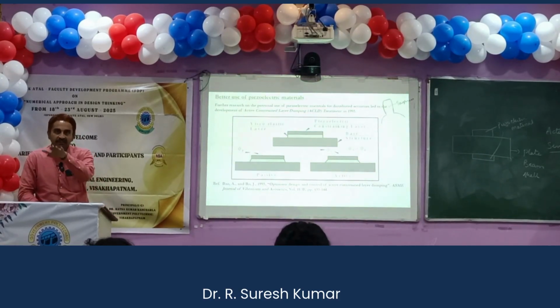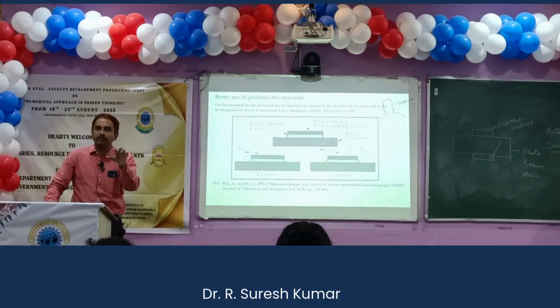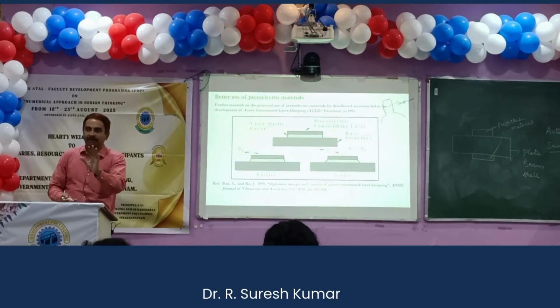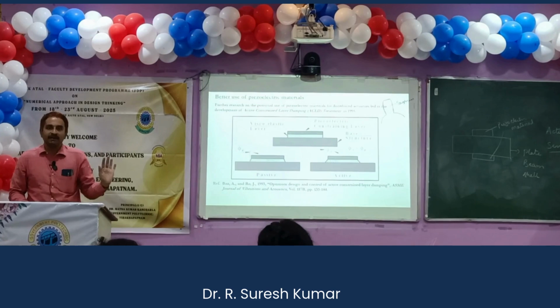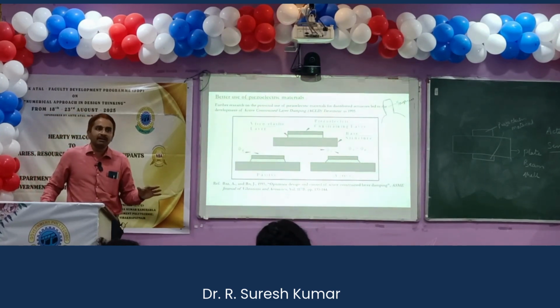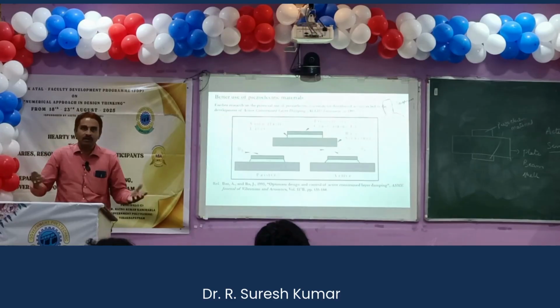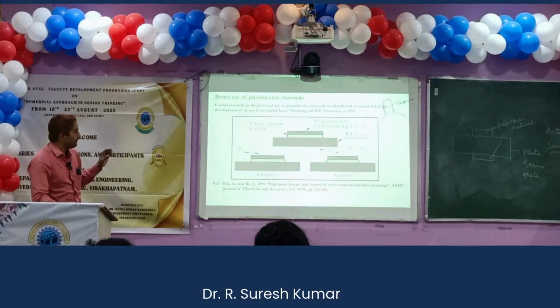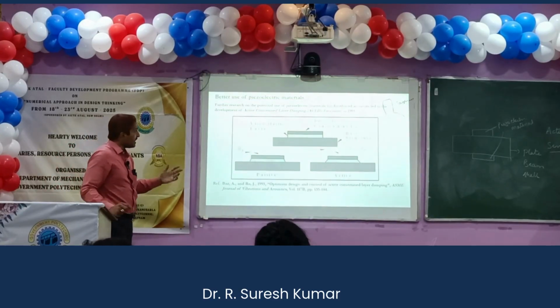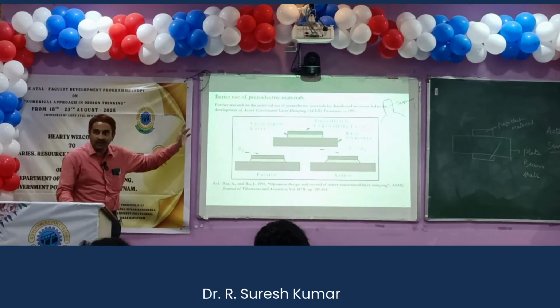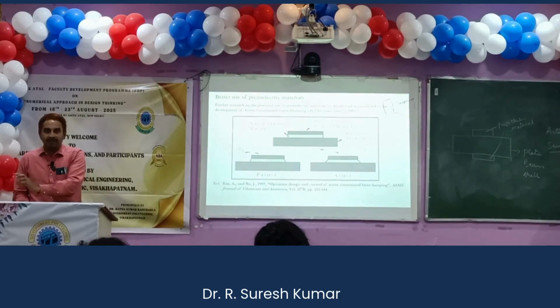Instead, between the piezoelectric material and the base structure like a beam, plate or shell, if you put a viscoelastic material, then the output that we want increases manifold. That has been the basic idea behind the development of what is known as active constrained layer damping treatment.